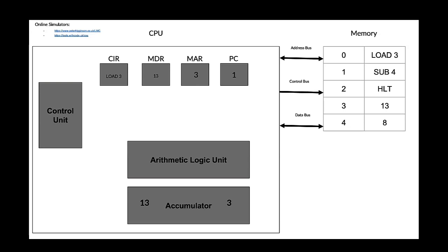The value of location 4 will be fetched by the CPU and sent to the ALU. Now the subtraction can be done. The number 13 that was stored in the accumulator will be sent to the ALU and the subtraction will be done. And the result will be sent back to the accumulator to be used in another calculation or to be stored in the RAM.